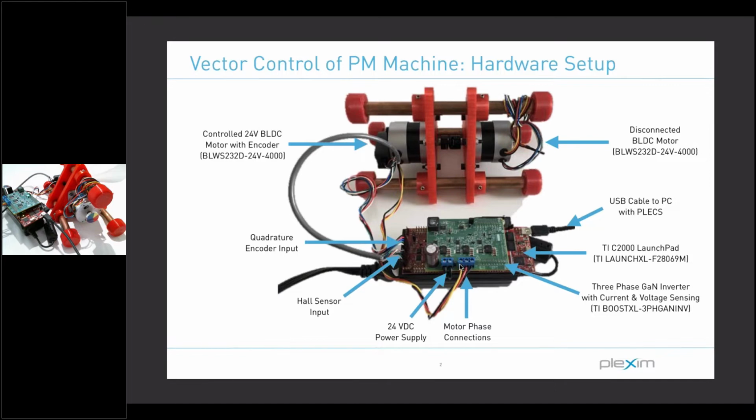So when PLECS is communicating with the control logic executing on the microprocessor, I'll refer to that as using the external mode, which means that the PLECS schematic is synchronized with an external source. In this case, it's going to be the LaunchPad device.